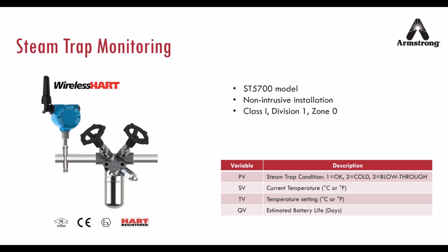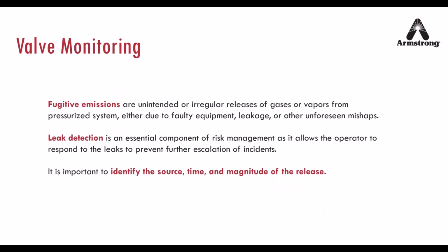The next application is valve monitoring. The main focus is on your fugitive emissions and leak detection, and the importance is actually to identify the source, the time, for how long, and the magnitude of a release. Is it just sizzling, or is it just wide open? And this is what you really want to do.